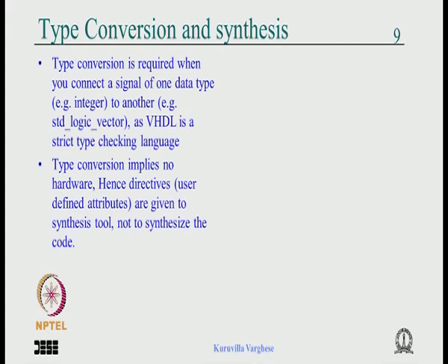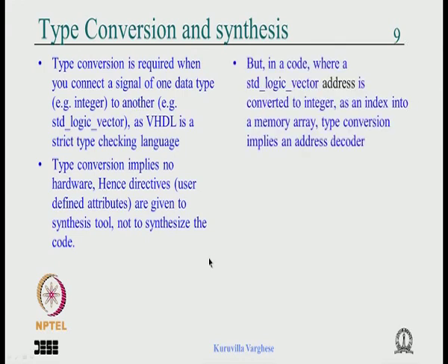Similarly there is an issue with the most significant bit and least significant bit. All that is guaranteed by this, and the code we write for conversion should not be synthesized. So that is indicated in the library that synthesis should be off during that conversion.